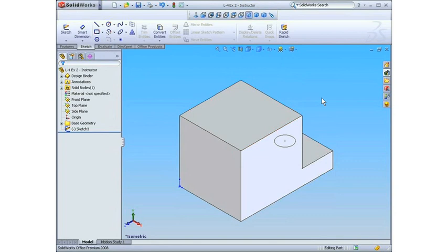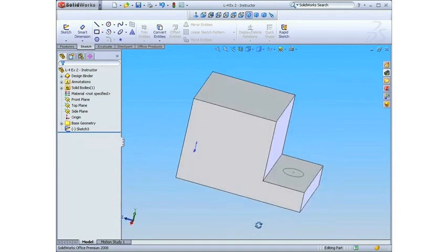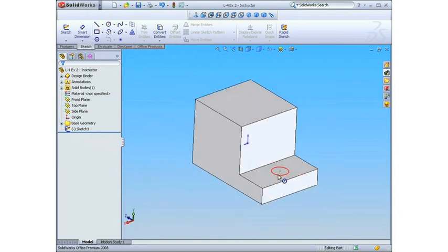Now there's a few things we want to look at in this lesson. We're going to look at construction geometry, and we're also going to take modifying existing geometry a step farther. If we notice, we've got one sketch outside of our base geometry that is appearing to be gray on the face of our object. I don't believe we've seen a gray sketch before. A gray sketch is a sketch that's visible, and it hasn't been hidden because it's not yet attached to a feature.